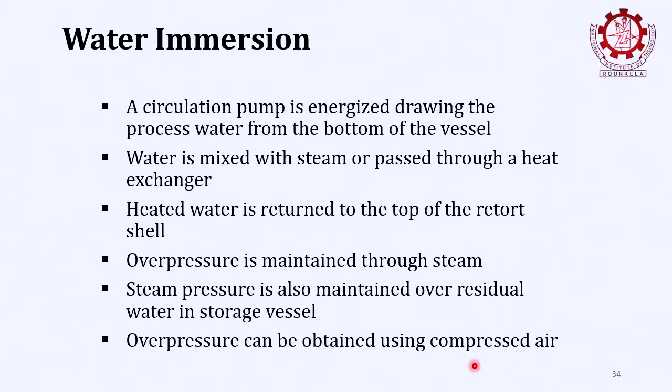The overpressure, I was saying, you can have using steam or you can have compressed air. Either way you could obtain the overpressure, because if you don't have overpressure, you cannot have the water at more than 100 degrees C. So you have to have some overpressure, which you can achieve either from steam or from the air.